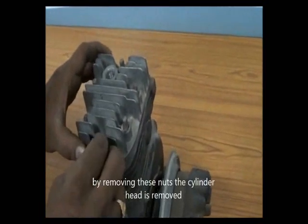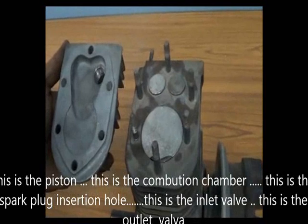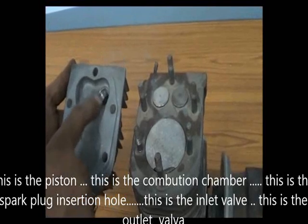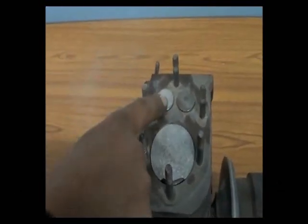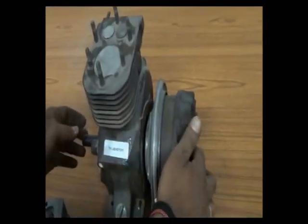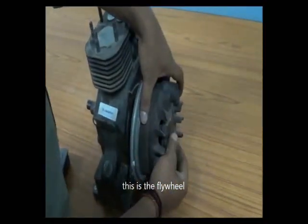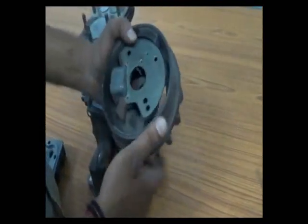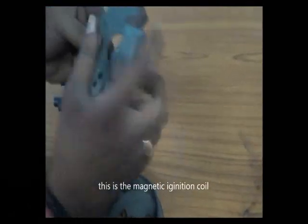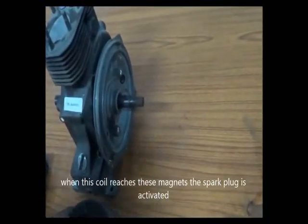By removing these nuts, the cylinder head is removed. This is the piston. This is the combustion chamber. This is the spark plug insertion hole. This is the inlet valve. And this is the outlet valve. This is the flywheel. This is the magnetic ignition coil. When this coil reaches these magnets, the spark plug is activated.